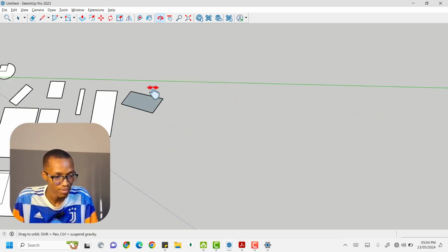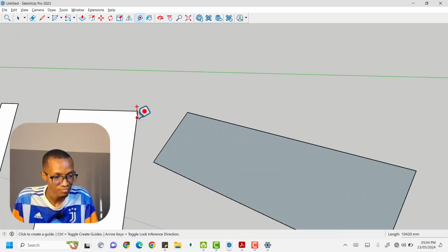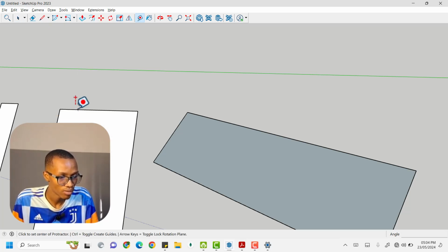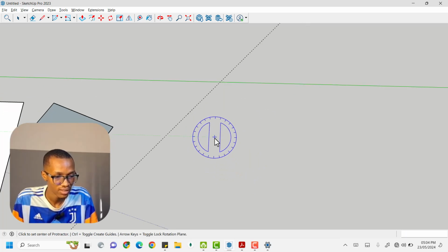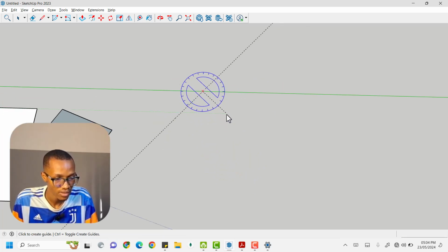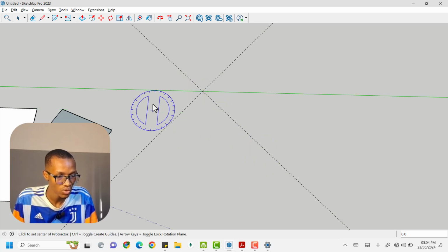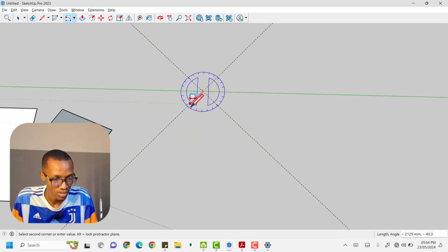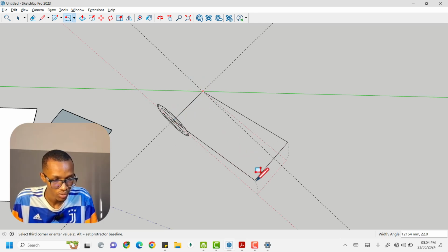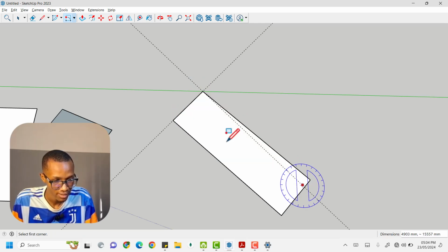All right, so let me just quickly do a detour. If you come to the protractor, it's like the angle version of your tape tool. So I use the tape tool at this angle, and I just tape this and bring it out like that, like so. If I come to the rotated rectangle and I just want to do a rectangle along this axis, I'll put it here, and then I'll pull towards this line, and like that I did my rectangle towards that axis.